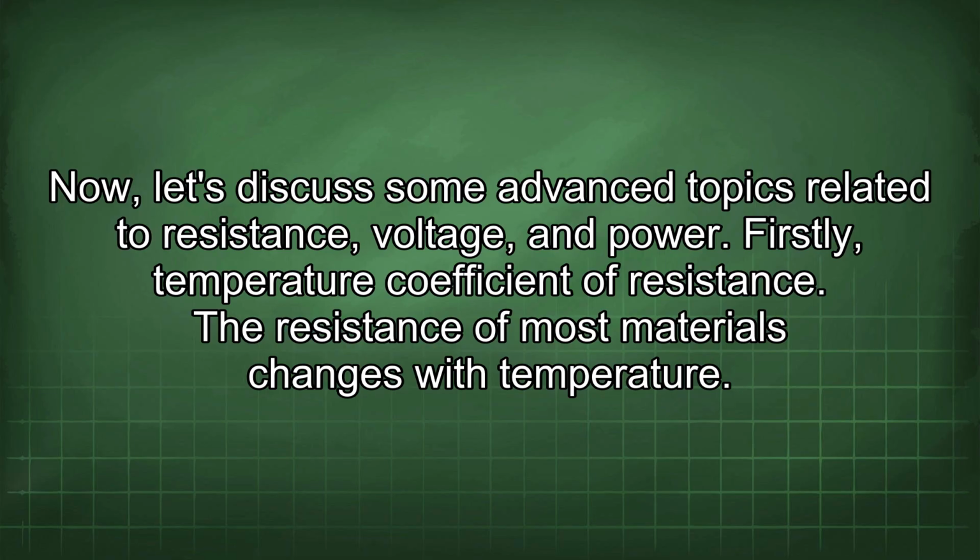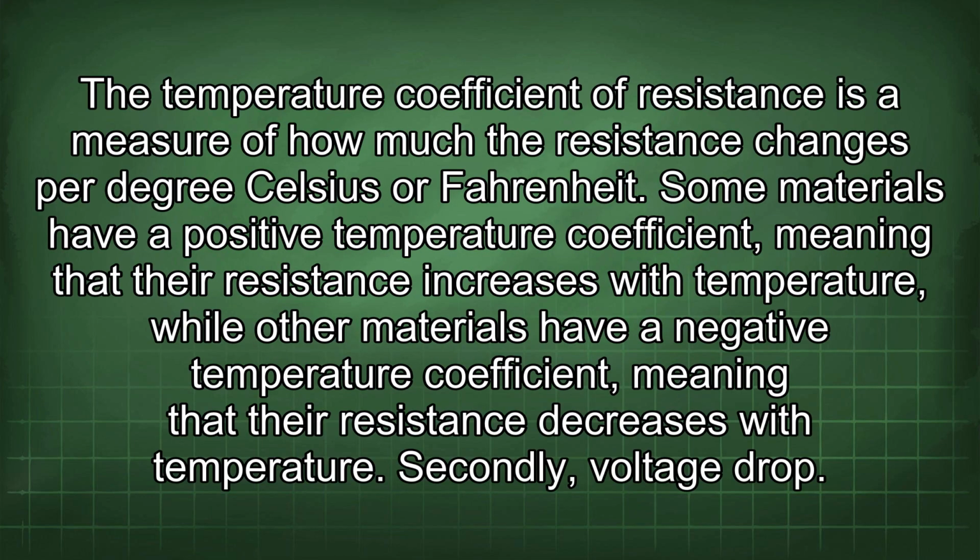Firstly, temperature coefficient of resistance. The resistance of most materials changes with temperature. The temperature coefficient of resistance is a measure of how much the resistance changes per degree Celsius or Fahrenheit. Some materials have a positive temperature coefficient, meaning that their resistance increases with temperature, while other materials have a negative temperature coefficient, meaning that their resistance decreases with temperature.